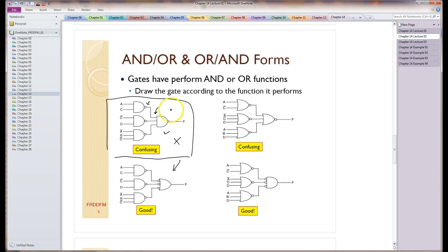The difference between these two forms is we've replaced that NAND gate with this form of the NAND gate. These are essentially AND-OR forms, which are SOP related forms, and it's actually doing an OR function there, so I'm going to draw that gate as an OR function. Remember, it's AND-OR. These are the ANDs. That's the OR. The nice thing about this circuit is it's drawn in such a way that interior logic levels match, and this is referred to as the famous bubble matching. And also this has a positive logic output, and there's no bubble on the output.